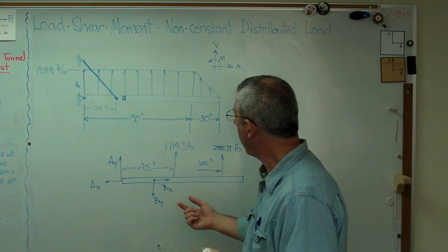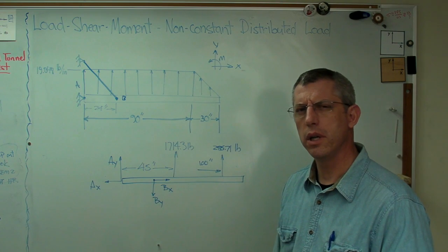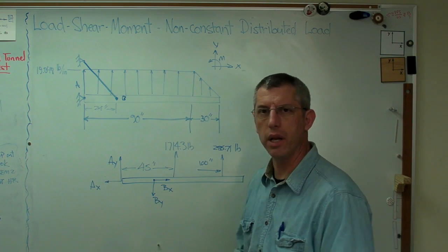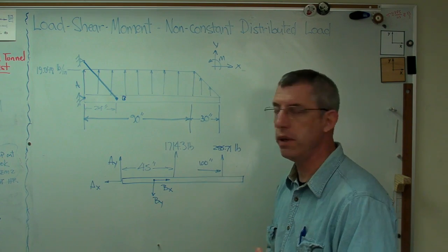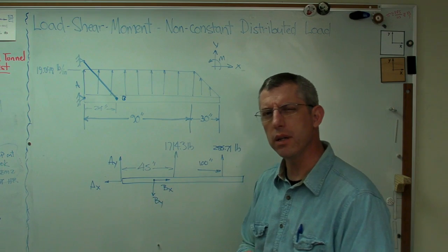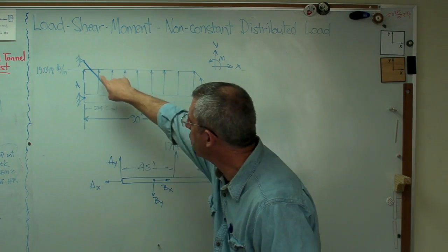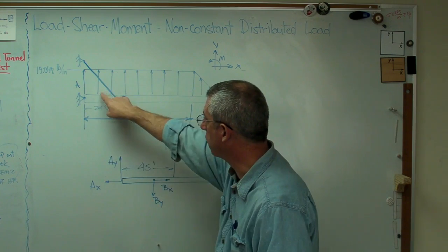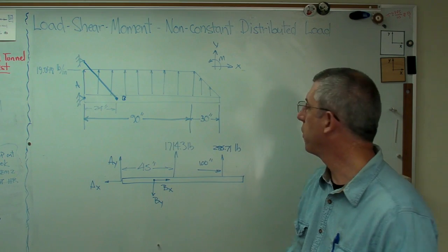Okay. I have, let's see, 1, 2, 3, 4 unknown forces, and I can only write 2 equations of equilibrium, can I? Well, I can write 3. Seems like too many, doesn't it? 4 unknowns and 3 equations of equilibrium. Well, I already know what that angle is, so since this is 45 especially, I know that Bx equals By. So there's my fourth equation.